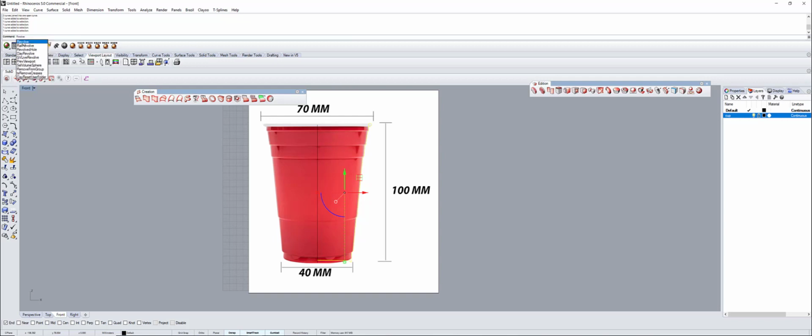You can see it over here. Rhinoceros is already showing me the name there. You know, it's going to show you what commands start with R and E. So it's going to show you a lot of options. So it's this one, Revolve. So you have to select first your profile curve, okay, and then Rhinoceros is going to ask you what is the start of the revolve axis. So our axis is going to be the center line.